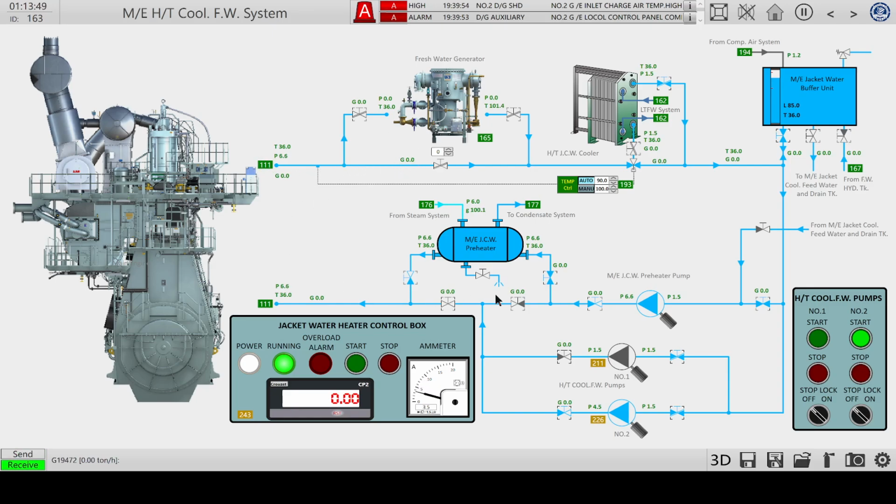Going back, this is not hot enough to use the fresh water generator, but we're going to set up the cooler if needed with this valve. Directs it automatically back. So let's check this cooler if it does have water from the fresh water system to cool.